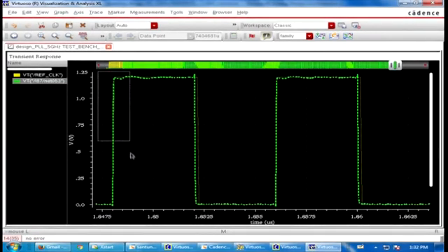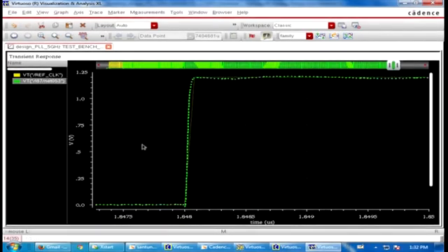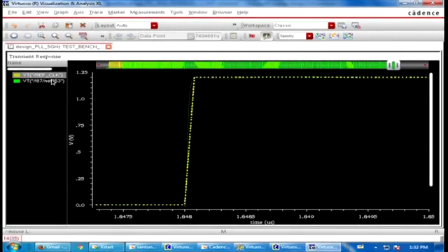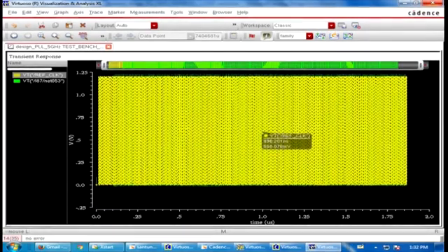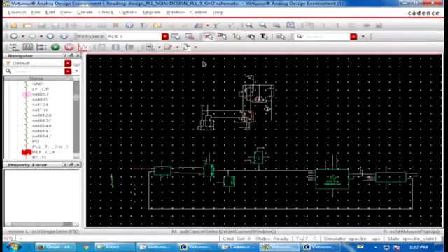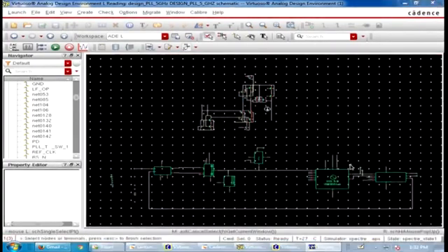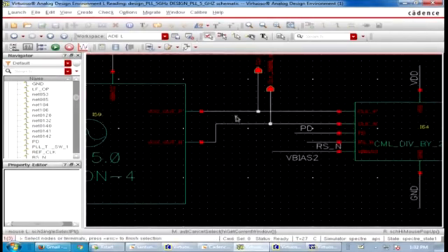Now it is the divided frequency, and so you can see the locked conditions. You can find the control voltage flattens out and my frequency and the phase are becoming locked. So you are having the same profile. And next thing is the 5 gigahertz frequency I want to show you. You see the frequency, that is the free running frequency of the VCO. Let's go to the VCO mode.